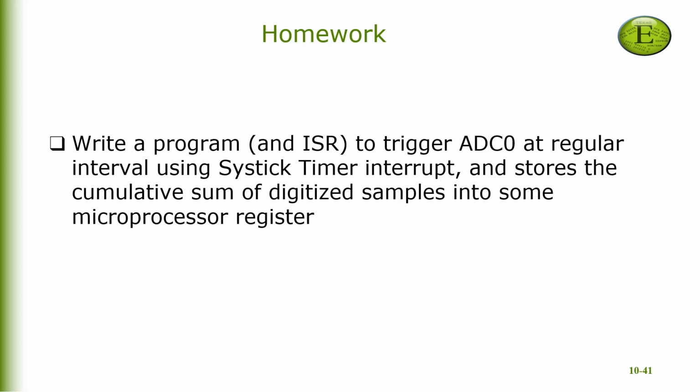With that in mind, there's a homework exercise for you. Write a program and the accompanying interrupt service routine that is going to trigger the ADC at regular intervals using the SysTick timer interrupt. So you're going to write the ISR for the SysTick timer that is going to trigger the ADC. And once the ADC has outputted the digitized input sample, you're required to store the cumulative sum of digitized samples into some microprocessor register.